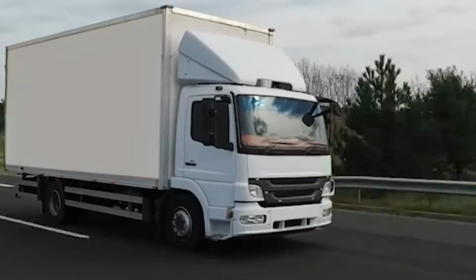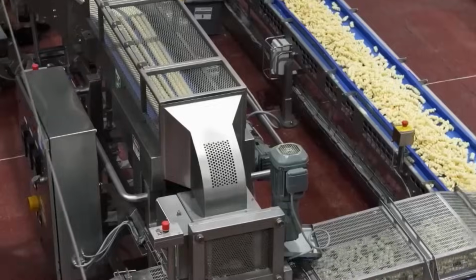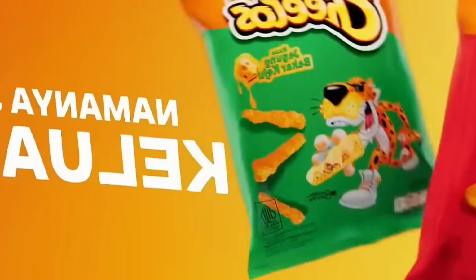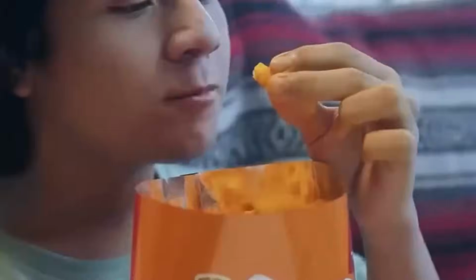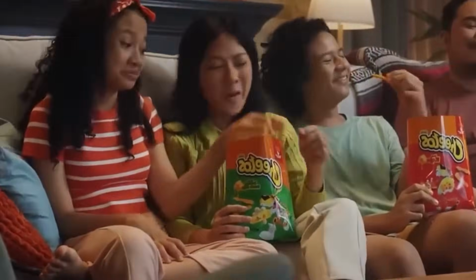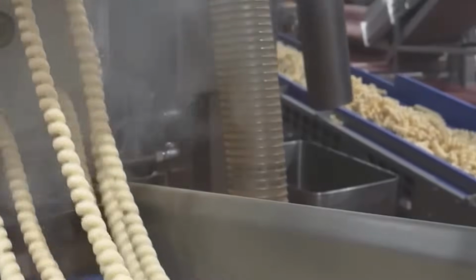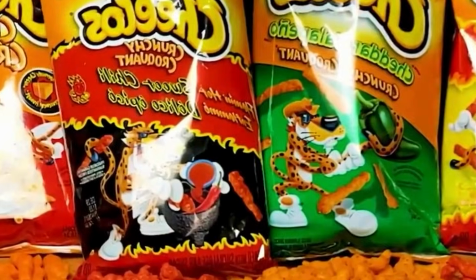Once cooled, the product is conveyed to the weighing and bagging station. Multi-head combination weighers are used to portion the product into precise fill weights, typically between 15 and 300 grams, depending on bag size. Each head drops a known quantity into a central chute when the calculated sum matches the target fill weight. The portioned product is dispensed into pre-formed bags or into a form-fill seal machine.